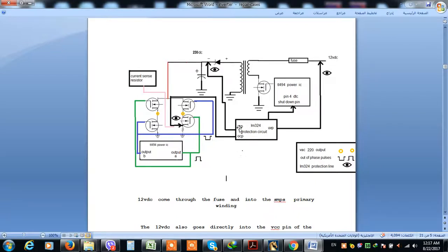Here we have OVP, which is short for over voltage protection, and over current protection and under voltage protection. Of course, there are four comparators. One is observing this line, and once it's low, there will be a mechanism that I don't have to explain in detail, but it's the work of a comparator. A comparator always has a reference, and if this reference is violated in some way,